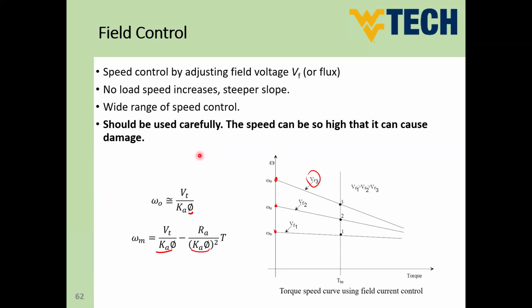If you reach that operating speed, your bearing may be damaged. So you have some limitations for the overspeed. Most of the time, we can use overspeed up to twice the rated speed or twice the no load speed, and the motor bearings should be designed to support that.